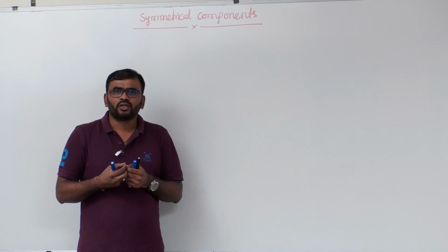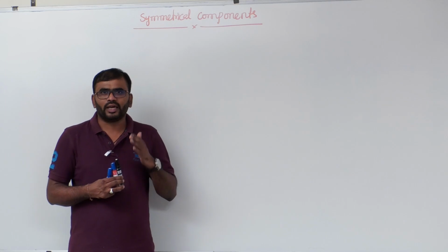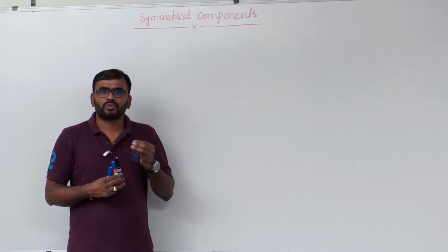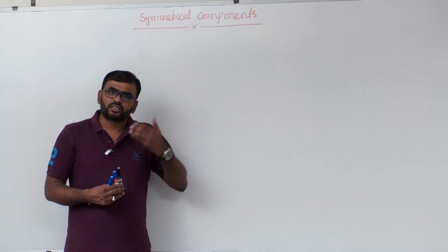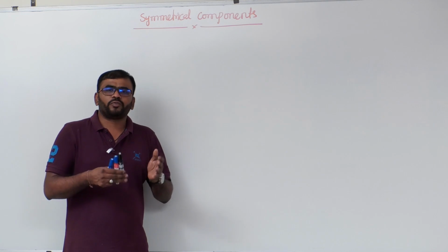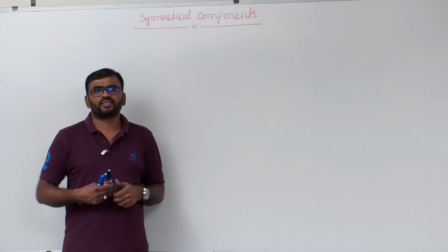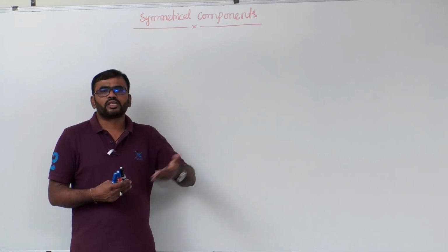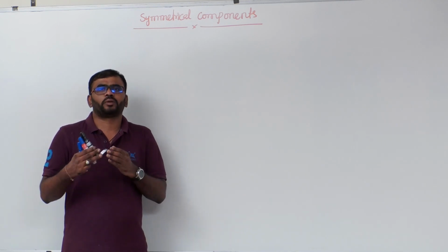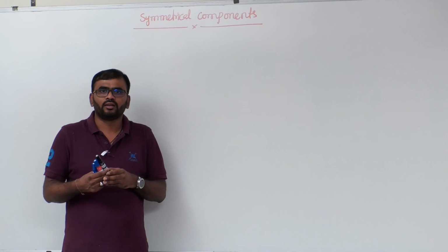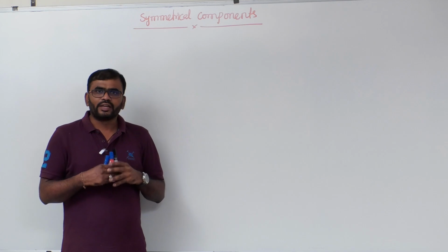And we already know that when the system becomes unbalanced, especially with respect to LG fault, LL fault, LLG fault, the system becomes unbalanced and symmetrical components are used to analyze such types of faults. Suppose it is a load flow analysis or stability analysis, the system remains in balanced mode, that is why we can go with the single phase approach. So, again I am saying, for solving an unbalanced power system or to do the analysis on LG fault, LL fault and LLG fault, the symmetrical components are introduced.